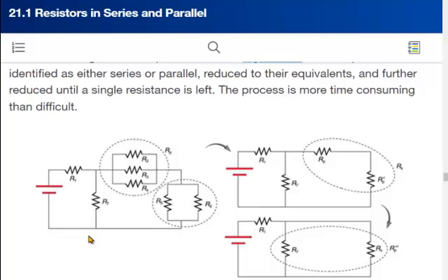For this particular one here, the normal, so to say, combinations of series and parallel circuits, all we have to do is combine them in series, combine them in parallel, apply Ohm's law, that kind of thing. One of the clues to analyze a circuit like that is to look at where the junctions are. For example, there's a junction here, and here we're going to look at resistor 1 and resistor 7. Yes, resistor 7 is after resistor 1, but they are not in series because there's a junction in between. So hence we ought to do something else.